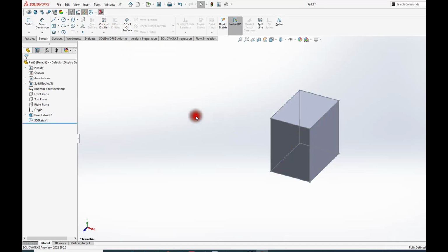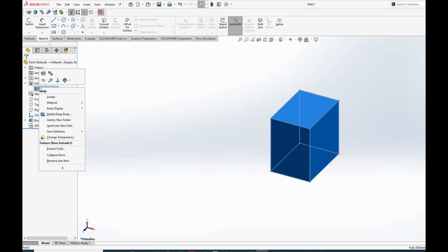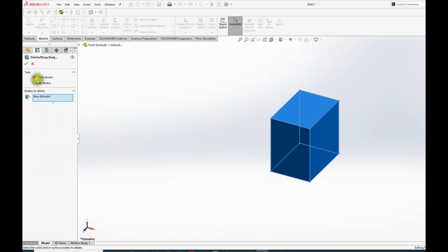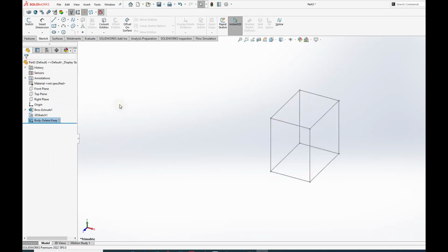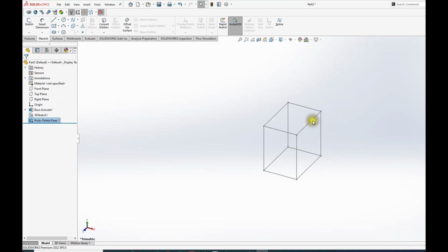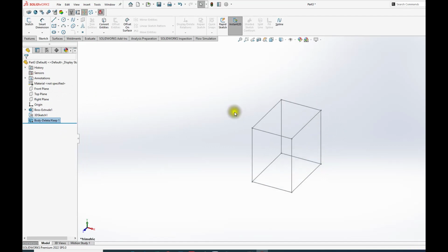And now this is the nice thing, go here on solid, and you're gonna remove that solid. Not that you are really removing it, but at least you are deleting from the bodies, delete bodies, yes. Now it's gone, and you have all the edges ready for doing whatever you have to. That's very simple. You don't have to go by one or so. They are all there. So now the next part is called weldment.